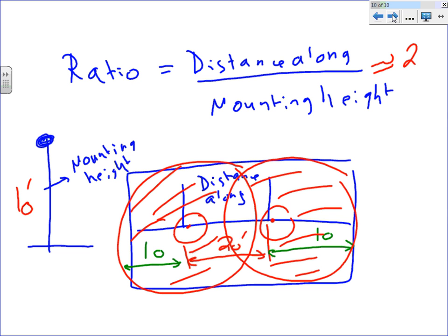What we've done right now is just the direct light, just from the fixture calculation. Reflected light is a much more complicated calculation, because not only do you have to do a calculation like what we did right at that point, that's coming from every fixture, but you also have to shoot it to the wall. So you need to know the reflection factor of this wall, right? And then see how much of this light is going to reflect and go right at that point.